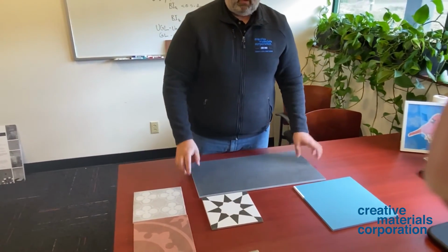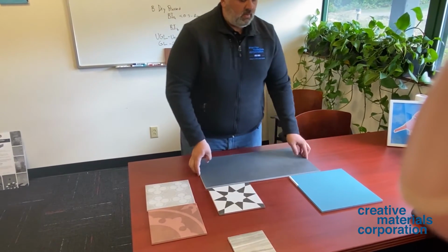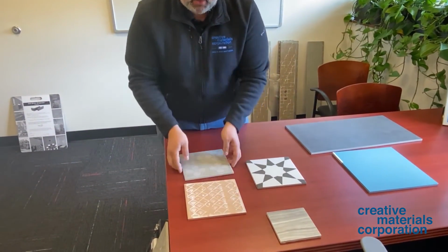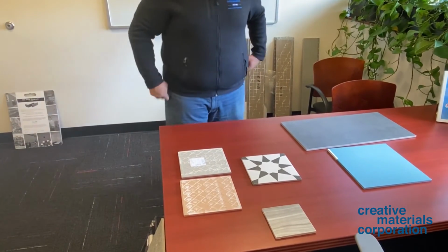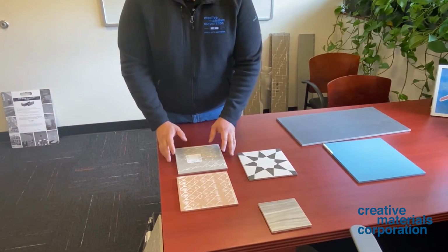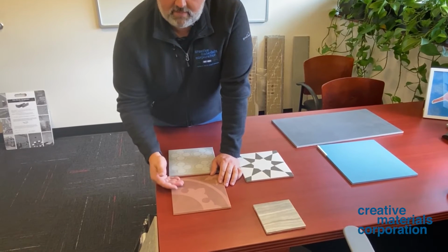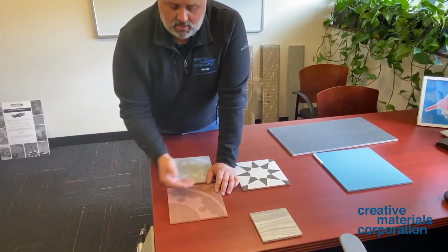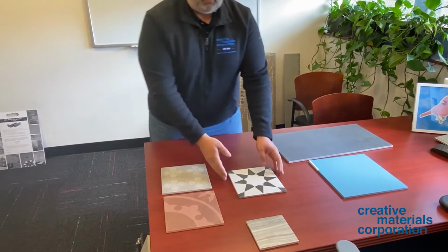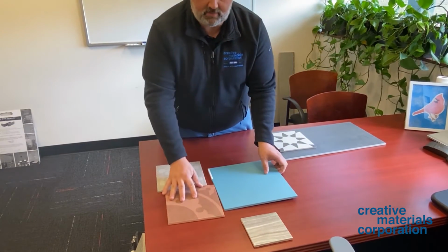Okay, so in the past we would say through body, glazed color body, glazed non-color body. Well, now we have these other products that are over here, similar to this one, but if you look at the back, the body color is the same as the surface, or coordinating enough. These are not, however, glazed tiles, because with the advancements in industrial glazes now, we're able to print glazes directly on the tile without the engobe layer, which allows the glaze to absorb into the body of the tile, making a fully vitrified product. So while it's similar in look to this, technically it's closer to this.